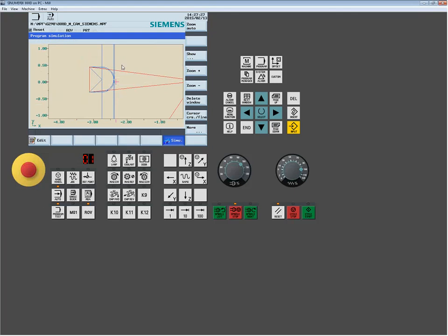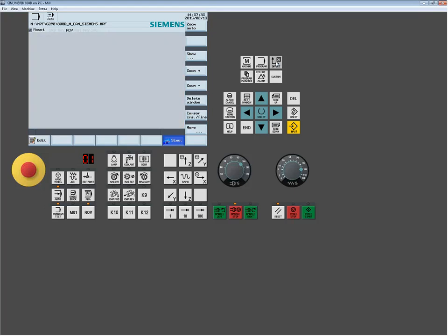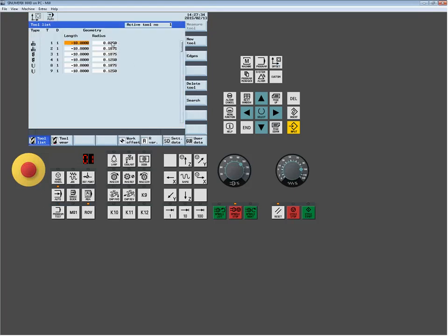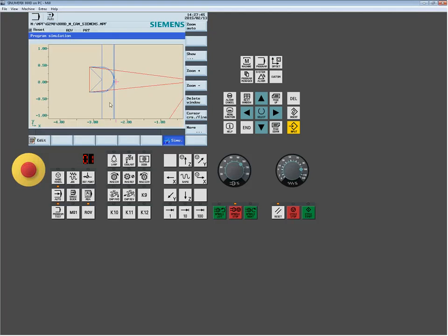So normally, this is how most guys run their machines when I'm dealing with CAM, and I'm outputting cutter compensation. They establish all of their tools at 0, and they'll put small incremental values here, plus or minus. Like if I was to set this value to a negative 25, I'm going to now see the exact same path, but now there'll be a new line on the right side here.